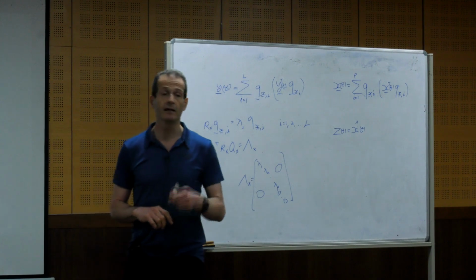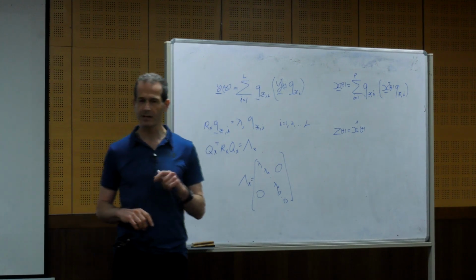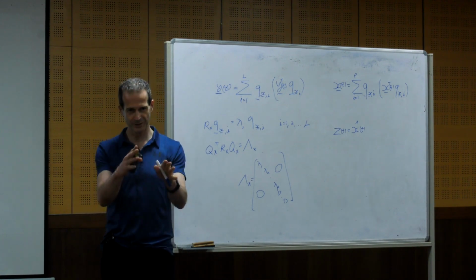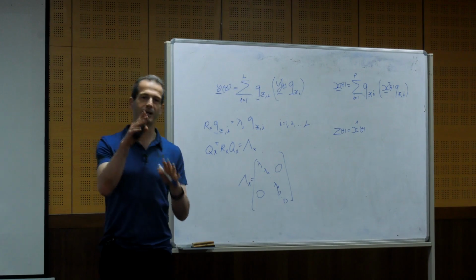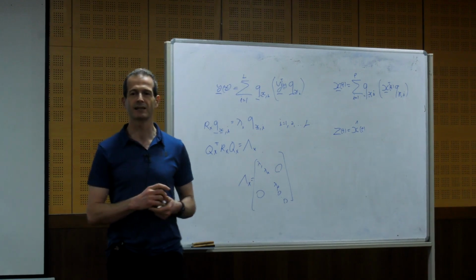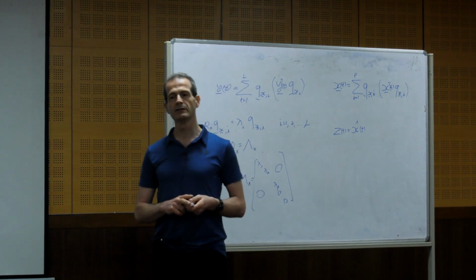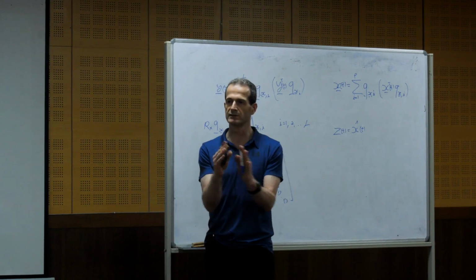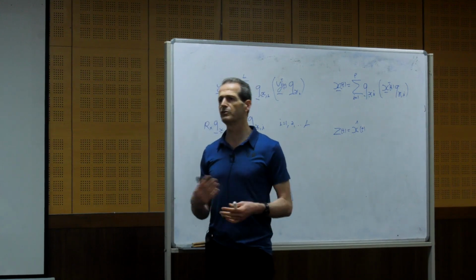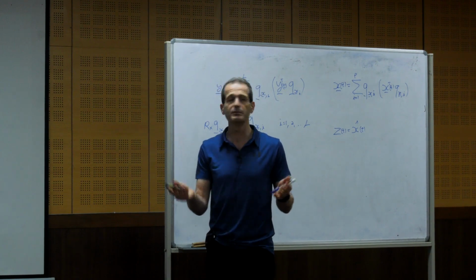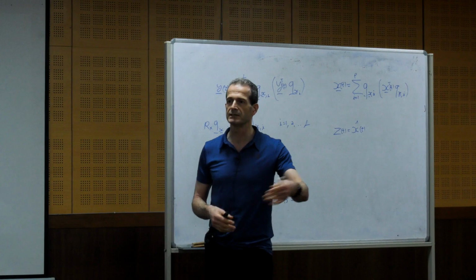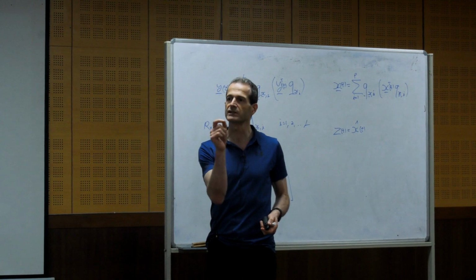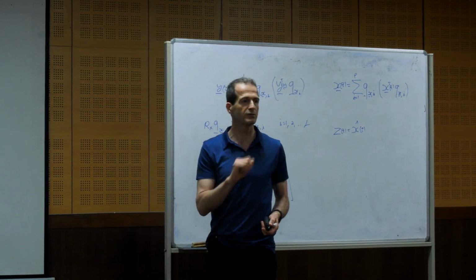Exactly. Okay, by windowing. Actually, I wanted two answers. Windowing, that's good, because you started with this, I will talk about this solution. If we window the speech signal into intervals of a few tens of milliseconds, 20 milliseconds, 30 milliseconds, 50 milliseconds, during this interval we have just a small portion of the speech phoneme or some part of the speech signal.